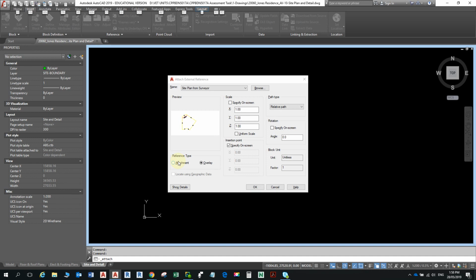Yeah. All right. So we had a case where we couldn't set the relative path, and we discovered in the end that the actual drawing file was probably saved on a USB, but the site plan was saved on the C drive. So they've got to be in exactly the same folder, the same drive, everything. Either both on C drive or both on USB. Exactly. Yeah. The relative path cannot work across drives. Yeah. All right. So let's do that.